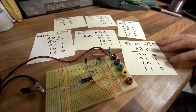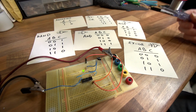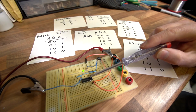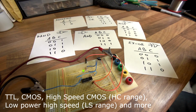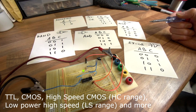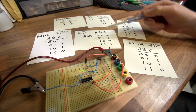Okay, so I hope you've enjoyed this brief overview of logic gates. We've shown you a couple of actual practical examples with using chips. TTL chips in our particular case, but they come in lots of different types of chip. TTL, CMOS chips, LS, HS, high-speed versions these days. Usually smaller than these in surface mount packages nowadays. But they all pretty much do all these different gate functions using these truth tables.